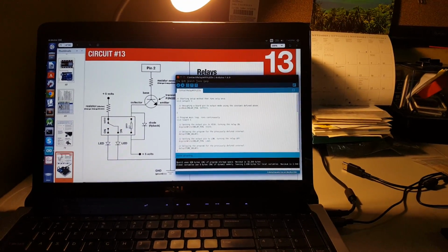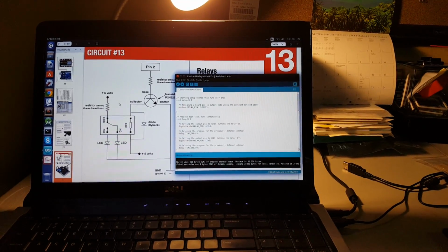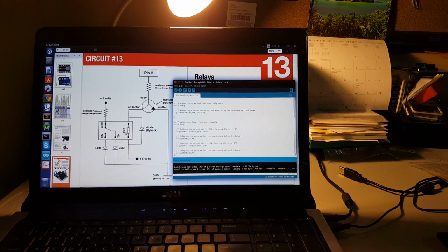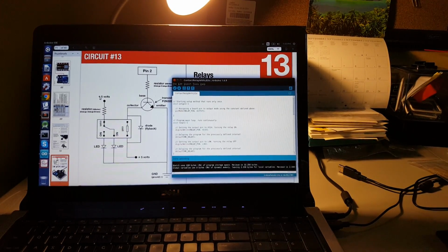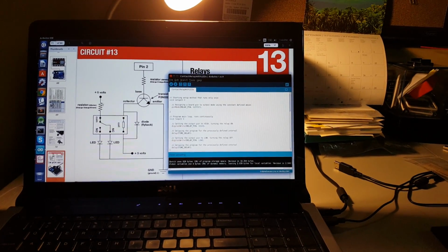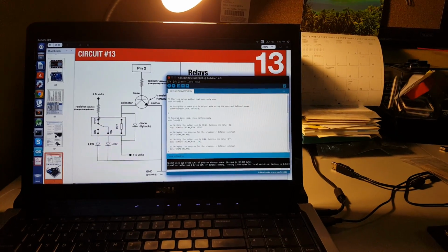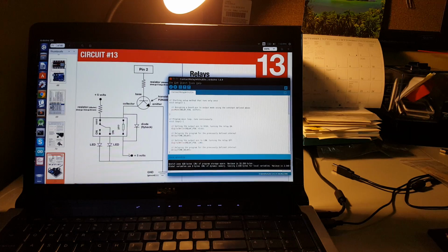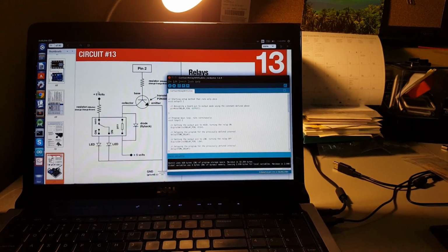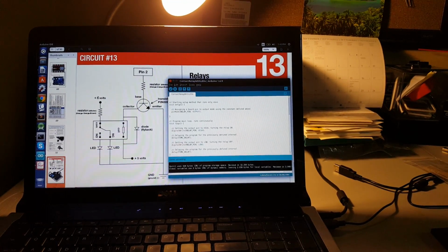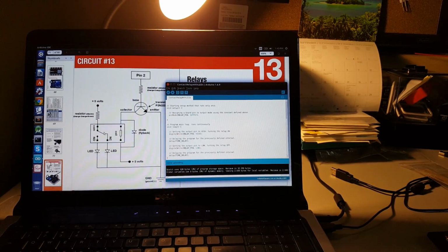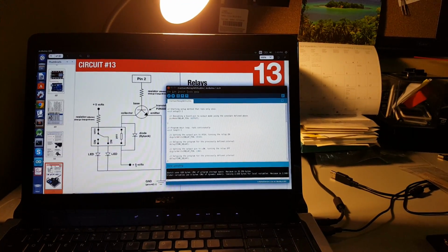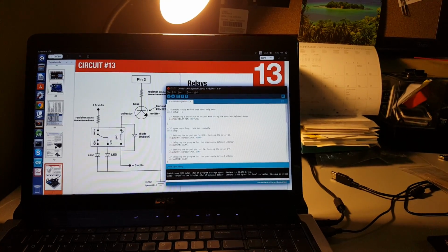The first thing to keep in mind is that there's 5 volts entering our contact relay, represented by this rectangle. It's getting the 5 volts at 2 points. One through this current limiting resistor that alternates between the two LEDs, and the second, which is going through the coil. Now, the 5 volts coming in on this side is always going to be flowing through one of the two, depending on whether or not the coil is actually conducting.